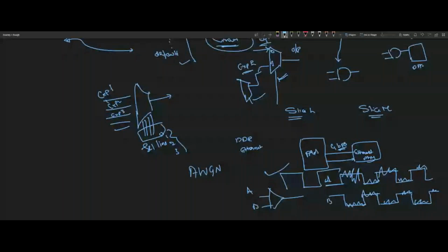For instance, consider an ASIC. In an ASIC you did a full adder, so all the physical design happens, the ASIC is manufactured, and that IC comes to you. Now you feel you want to make a ripple carry adder. What do you have to do? You cannot reconfigure that ASIC, because it is already a hardcore circuit designed by physical design and manufacturing. But in the same FPGA, the same IC, you can keep reprogramming the bit file and modify that IC into different functionalities.